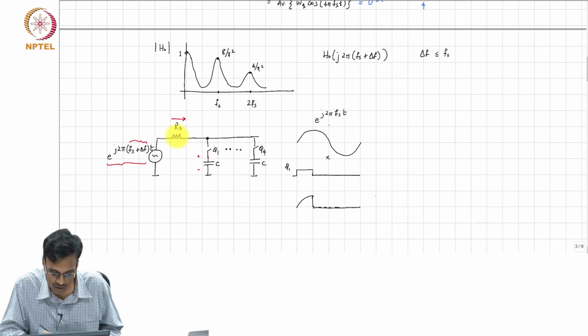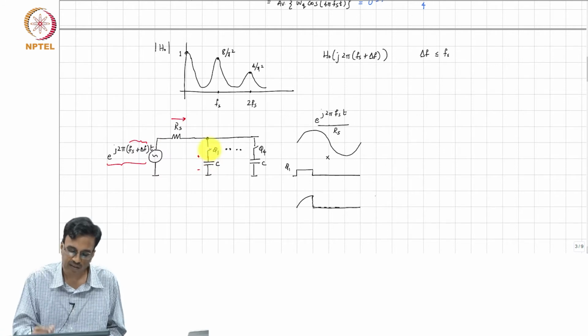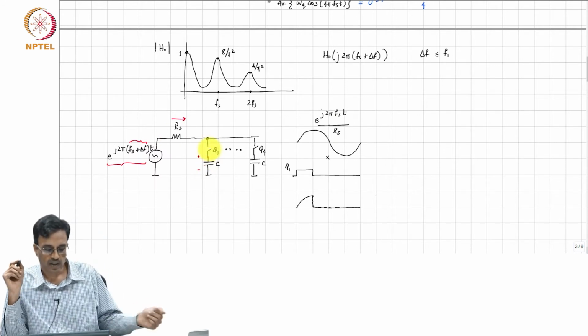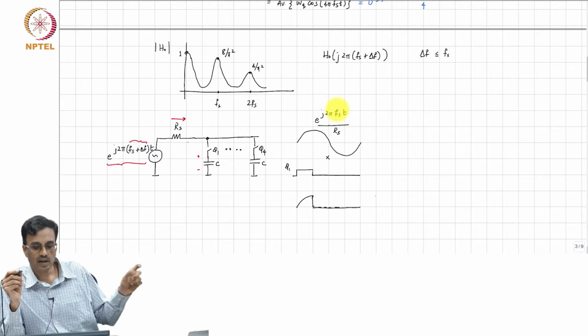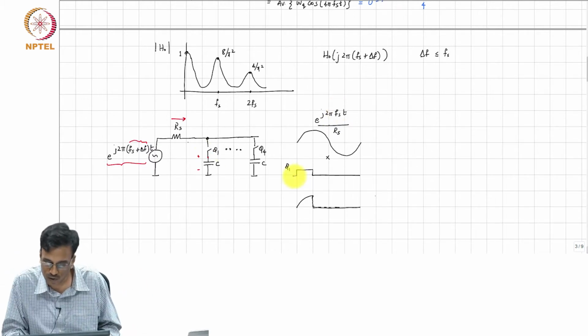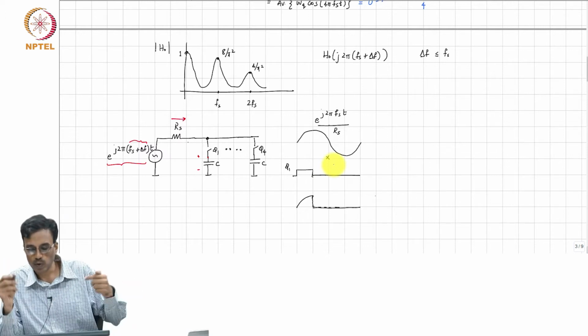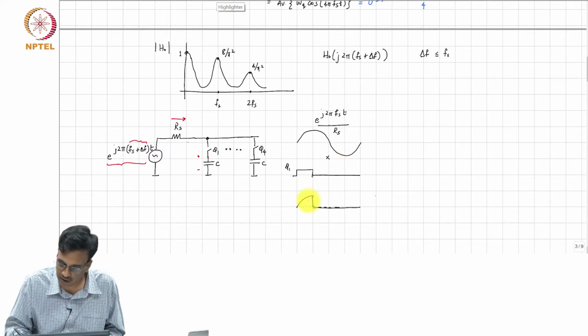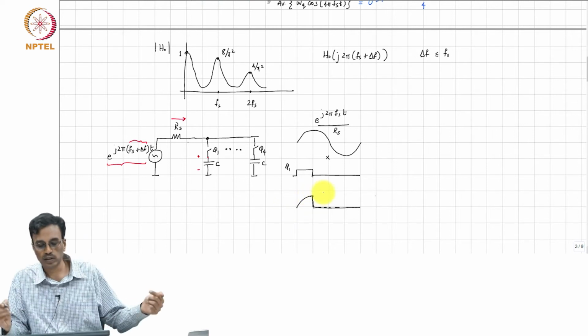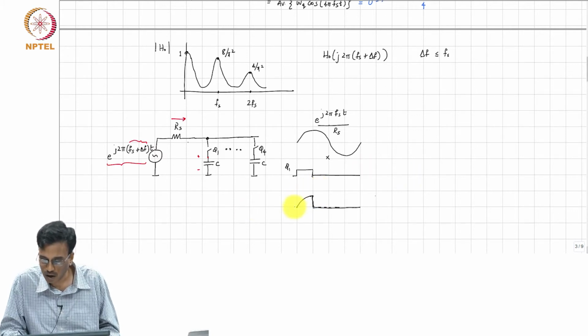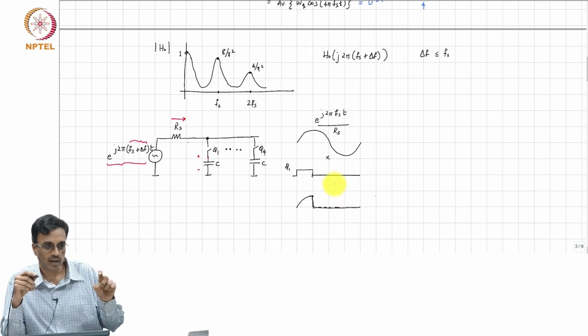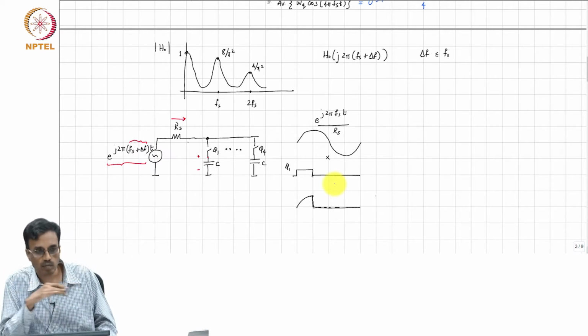so the voltage divided by RS is, if the capacitor voltage is constant during a clock phase, the RF current going in through the resistor is simply e to the j 2 pi Fs t divided by RS, that gets multiplied by this waveform, right, and consequently you can see that the waveform of the current going through the capacitor is something like this, right, and the capacitor is simply averaging this, correct, and therefore, there is some voltage established.